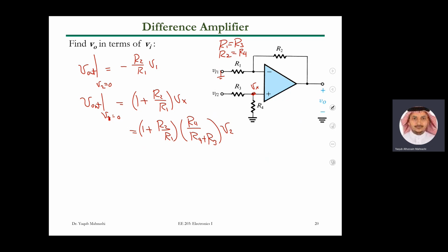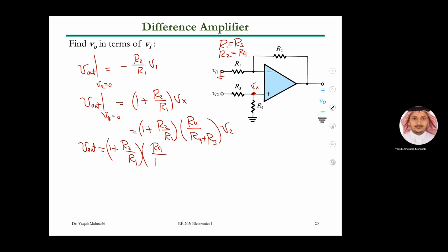So that's what you get. And then you can just add them together, right? So V out, at the end of the day, you'll get something like minus, let me have this one first, R2 over R1 multiplied by R4 plus R3, V2 minus this much, R2 over R1.